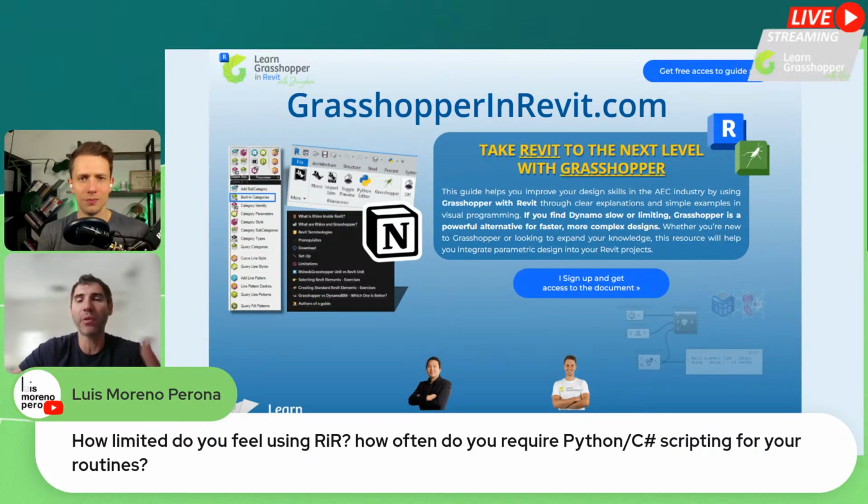So you have a face and you want to create a wall. This is something you can do in Revit, but you couldn't do it with Rhino Inside. So I created my own Python script: I can feed in a surface from Rhino and it creates the wall inside Revit. So a couple of things here and there might not be there, but you might be able to create them through the API. In general, I'd say they did a pretty good job.